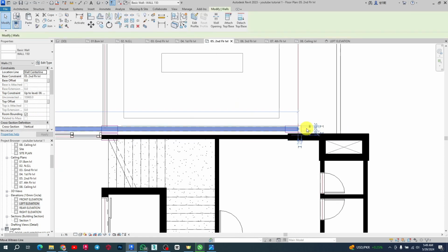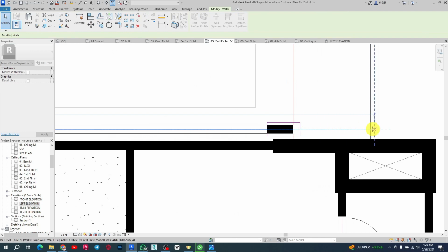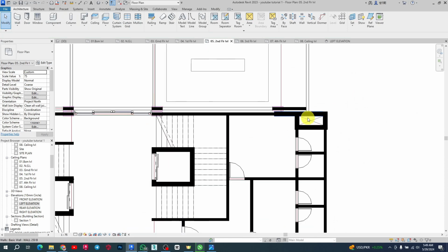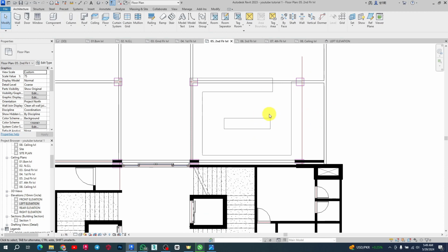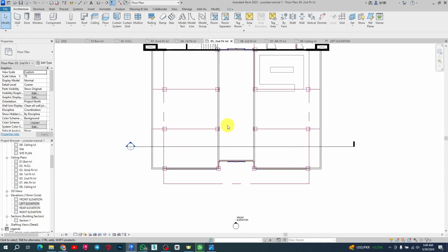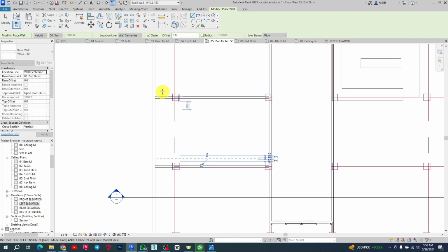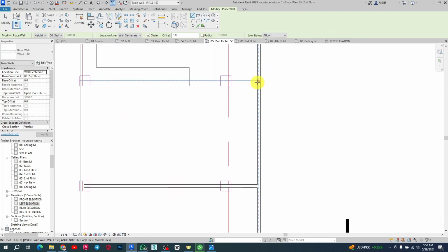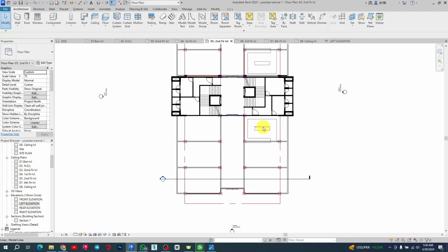And this expansion joint, the beam will continue. So I'll extend this part here. Okay, we'll expand that part there. The beam continues the same way too. So that is it. We probably might want to create an opening here just to give extra room to the person holding that store there. So let's have this one again, have this one here, and then we create these other ones here. I think that is it. Okay, so we have this.